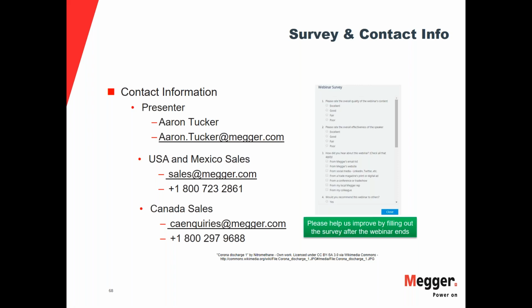Yeah, so there were a couple examples in there where you could see that the ratio or percentage error was in the negative. That means that whenever the test was done and the results came back, the ratio was determined to actually be less than the nameplate voltage ratio. So you can see that it would go negative versus a positive. As it goes positive and gets higher in error, it means that the ratio is not as close to the nameplate as specified.